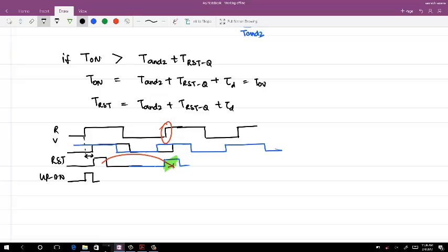Whereas when the phase error increased, your up minus down signal actually increased like this, right? So you are still maintaining a positive error, but now you missed one transition. Now your V signal is coming before up. So what you will see is that you actually get an up minus down signal here.